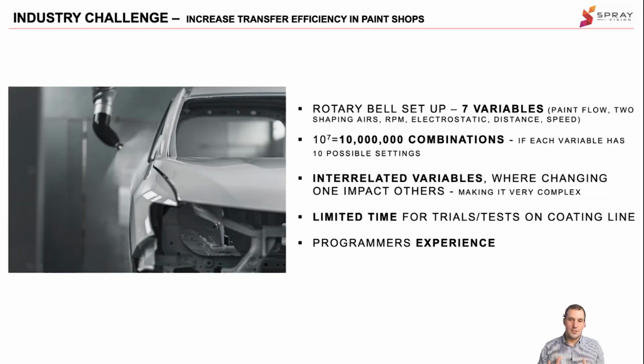Why is it so complex and so difficult? For a rotary valve setup itself, you need to find the combination of 7 variables: paint flow, shaping airs, electrostatic, distance, speed, and so on. If we consider just 10 options for each variable, it gives us 10 million combinations, which is an unbelievable number. If you also consider that all these variables are interrelated, you have a very complex, multi-physical problem, which, combined with the limited time for trials on the coating line, gives programmers a very hard task.